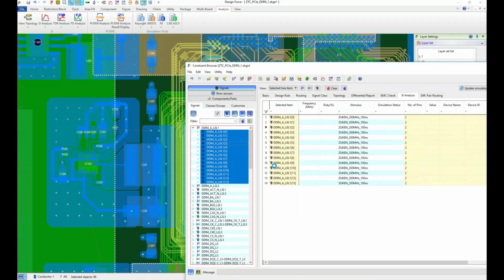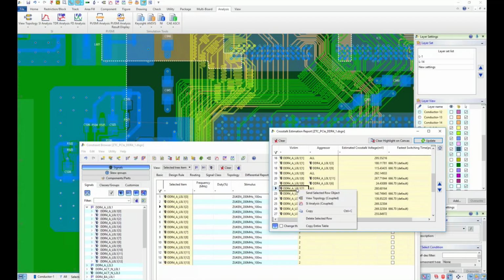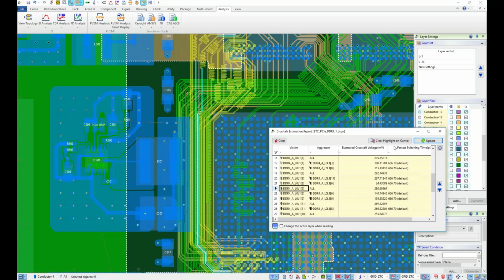And this allows you to determine where are your crosstalk hotspots on the board. And if you're interested then in the real figures of your crosstalk, you can pass this into the simulator and run a transient simulation on that crosstalk to get the real waveform and to figure out, okay, I do have an overall summing of 280 millivolt in that situation, but this is somehow distributed across the switching. So I would like to see the transient waveform to figure out if I have to do any kind of countermeasure in separating the traces further or doing a termination to clean some of the signals, or I can tolerate that amount of crosstalk.